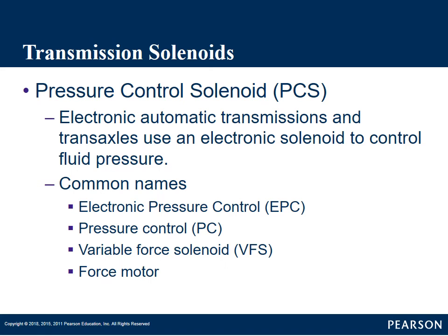We had one truck in the shop that we did some work on. We put the differential in it, and then it didn't want to shift. One of the checks we did, we hooked a pressure gauge up to it and hooked the scanner up. We could control the pressure control solenoid to see if it controlled our pressure. And when we get into diagnostics, we'll talk a little bit more about how to monitor and diagnose issues that might be related to our pressure control solenoid.